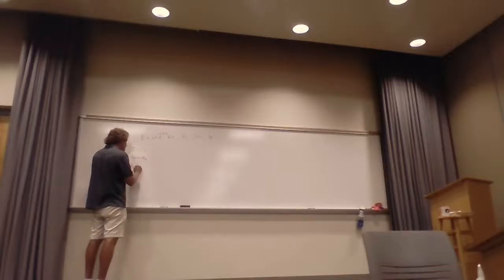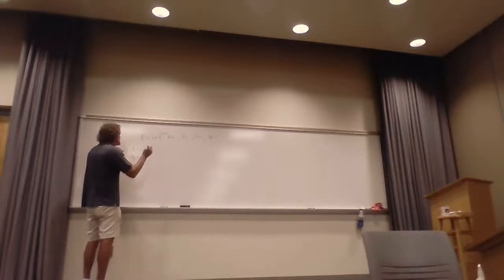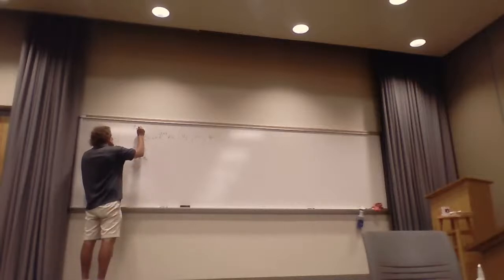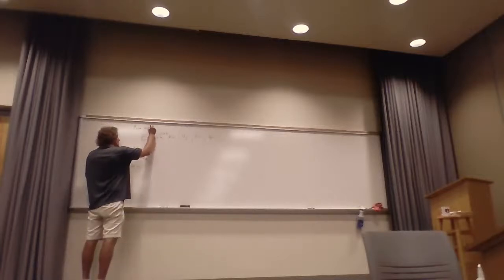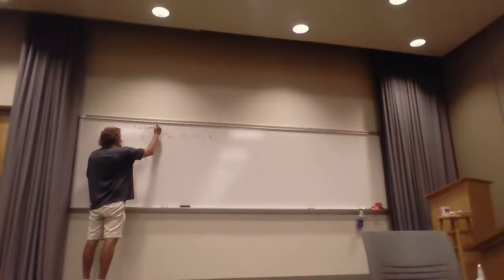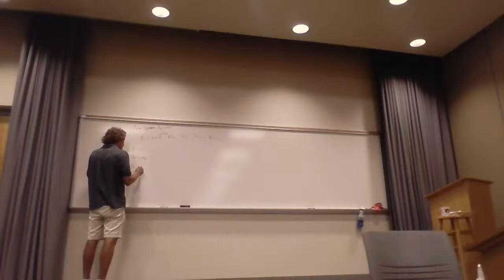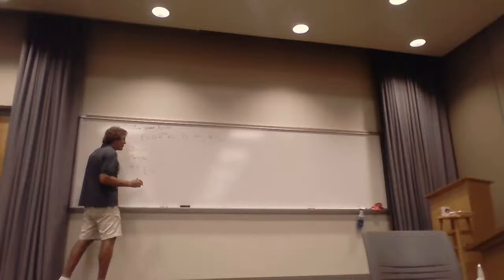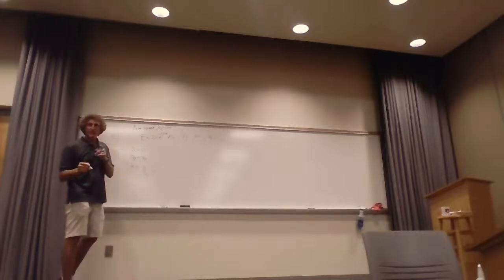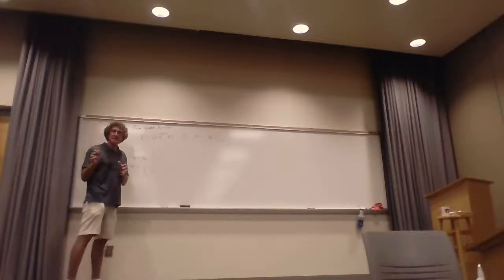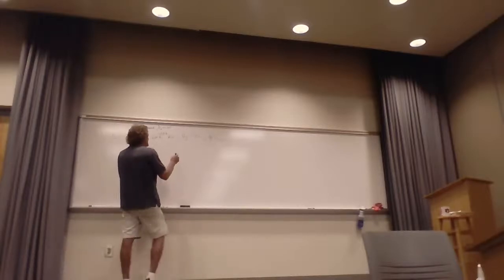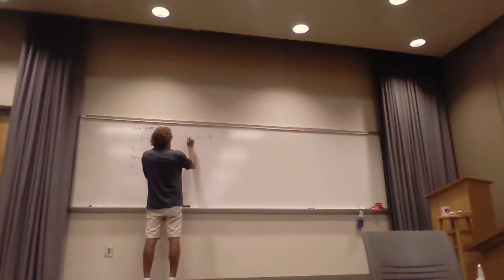Finally, for the H field, the only thing I cared about was the magnitude. Somewhere in there it says it's in free space, or in air. Eta naught is 120 pi for air, and therefore H is just the magnitude of E over eta naught. I want to say it's 0.057 amps per meter. Check me on that. Is that right? 0.053, sorry. So H is equal to 0.053 amps per meter.